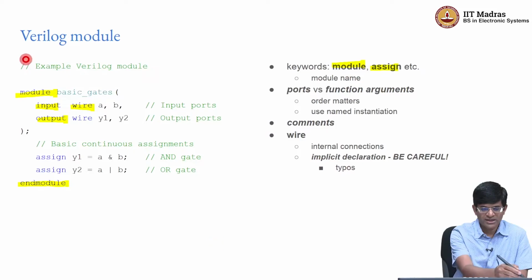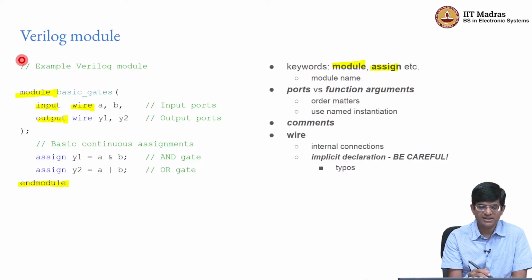Another thing that you might observe is you have comments, right, and this just looks like C, or to be more precise C++, because we use a // notation. The /* */ just like in C is also accepted for Verilog, which tells you Verilog's origins are related to C in some sense, and even in terms of how the language looks and the simplicity of the overall code, there are a lot of similarities to C. That should not trick you into thinking that knowing C means that you understand Verilog. There are some really fundamental differences between them that you really need to watch out for.